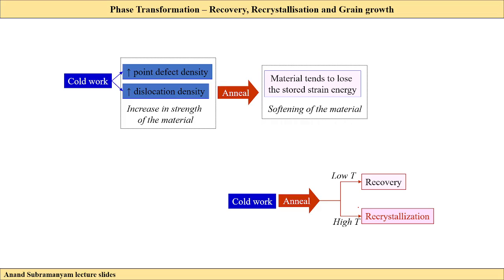So why? Again, in a fine grain structure, because of the small grains, the dislocations that are being created will have to jump from one grain to another grain. Dislocations can only move in a specified direction, which we call a slip system. For FCC, it is on the 111 plane and 110 direction. So these are the slip systems. Dislocations need that slip system for them to move, and they cannot abruptly change direction.